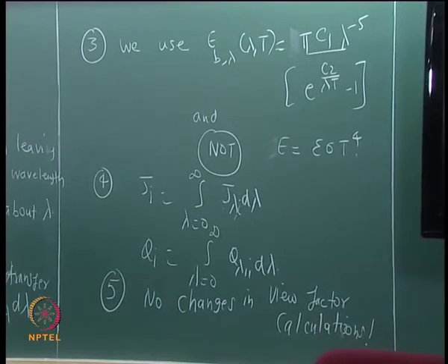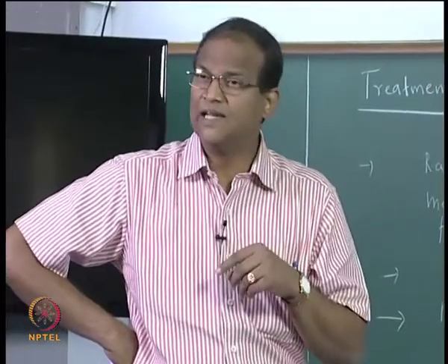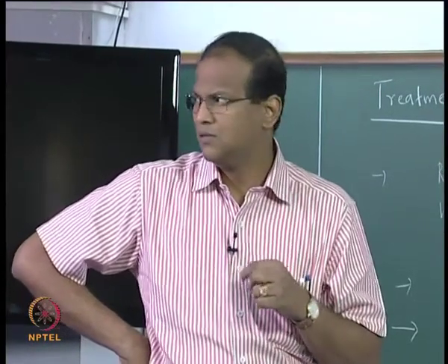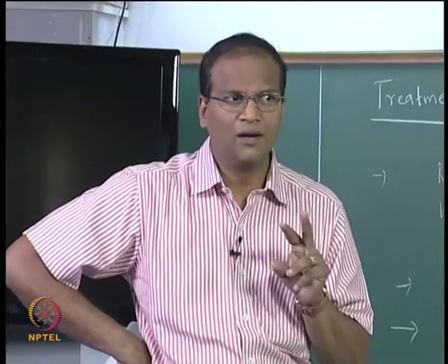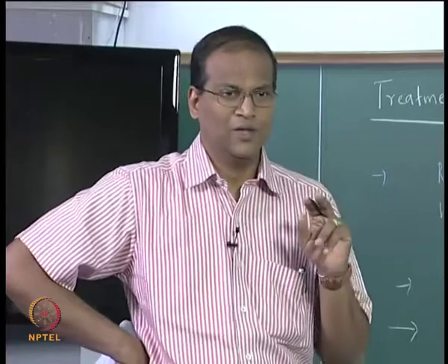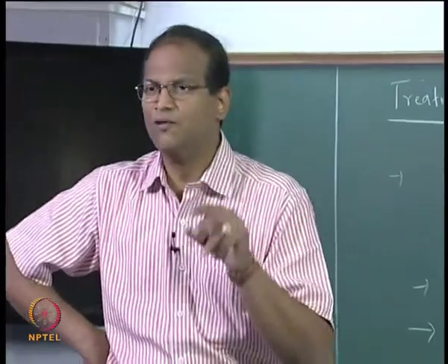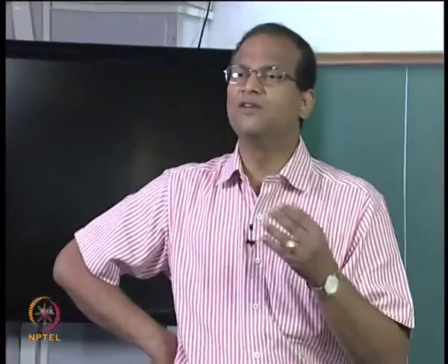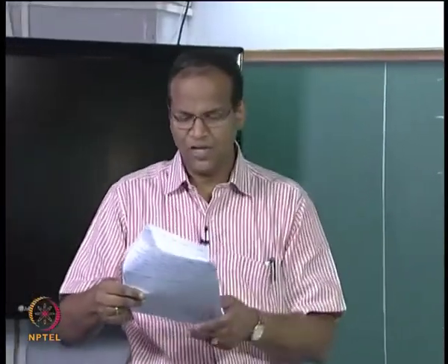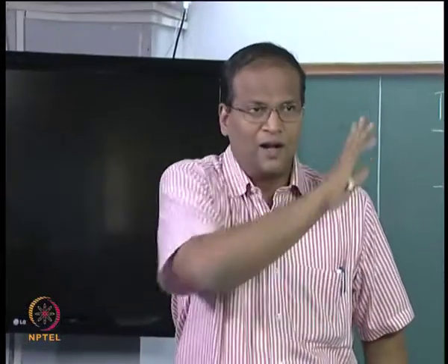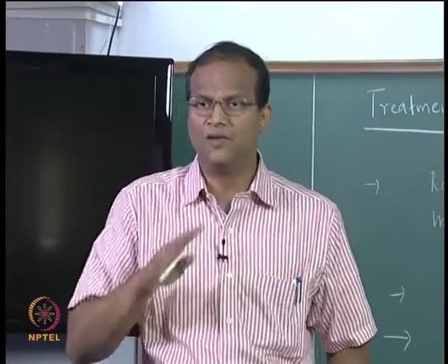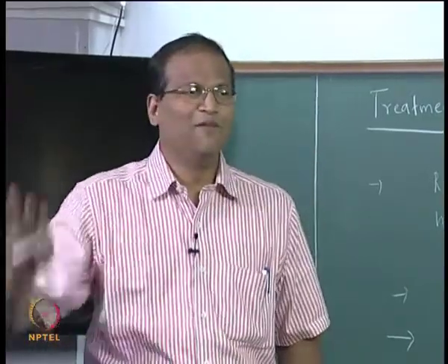So how do you get the reflectivity? It is spectrally dependent. Therefore you have to invoke Kirchhoff's law. To get the reflectivity you have to invoke Kirchhoff's law and say that alpha lambda is equal to epsilon lambda, okay. So this completes the formulation, this gives you the broad framework after going through these important rules, right. This is like COT or prerequisites. Once we have all this, then we write the formulation.